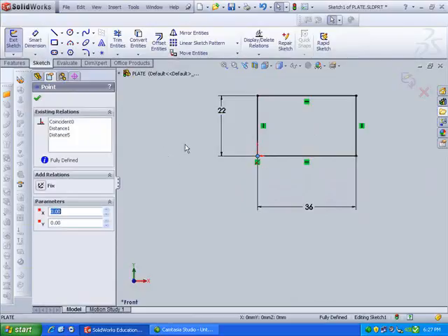When I select that corner, it's giving me a list of all the constraints that point has. It has 2 distances, one there, right? And you see the little grip light up. It's telling me that distance 5 is here and distance 1 is over here. Okay. It also has a coincidence, which is telling me that it's coincident to the origin. Let's just say that I really didn't want it coincident to that origin.